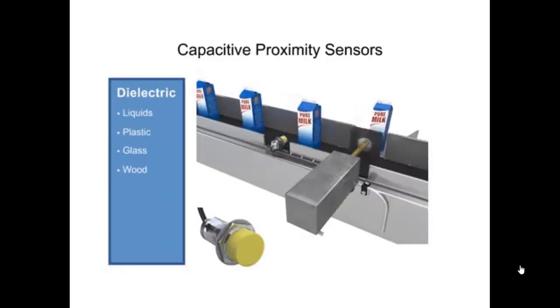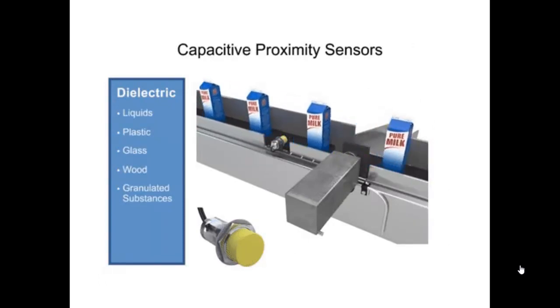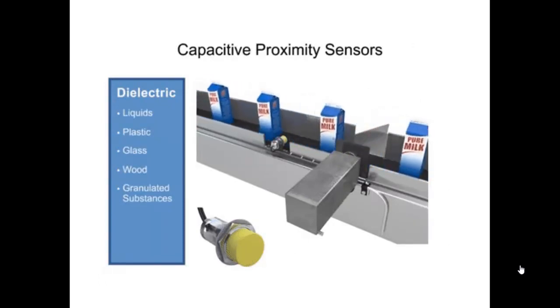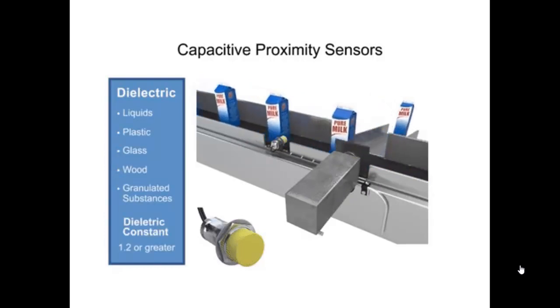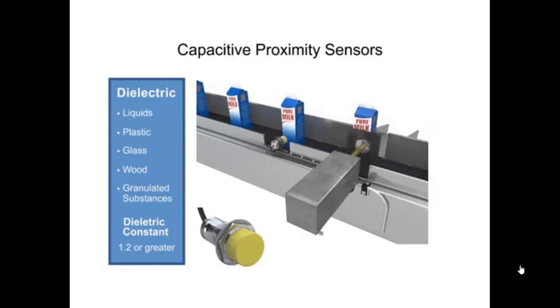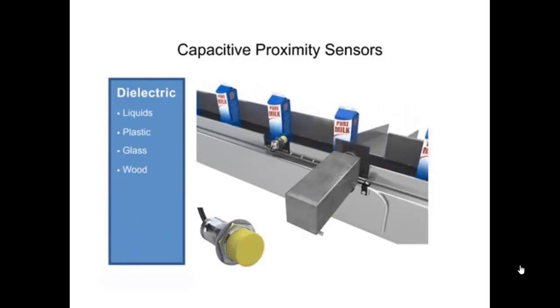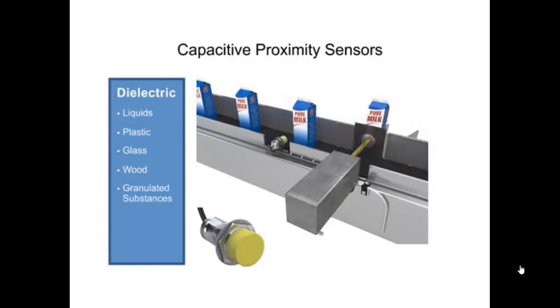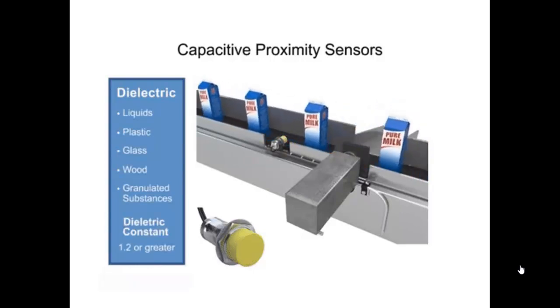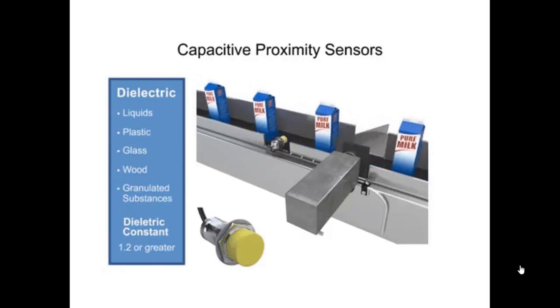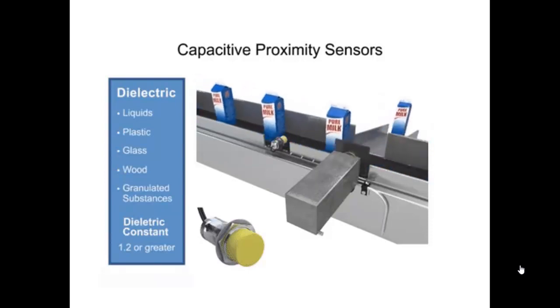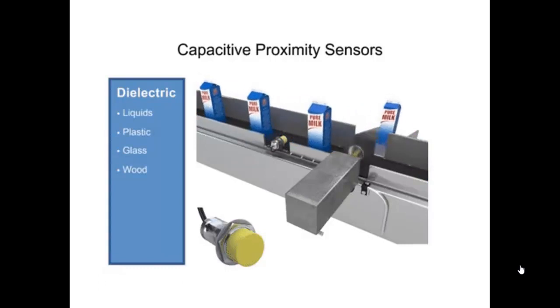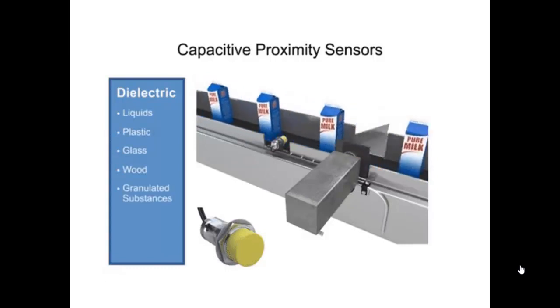They have a considerable application in the industries, where we can change the dielectric between the two plates, also by putting something like liquids or plastic. All those things can be put in so that we can use them in the packaging industries, where we can monitor, for example in milk cans, the type of liquid present, or whether there are any contents of glass or plastics. All those things will cause a change in the capacitance, because that acts as a dielectric medium.